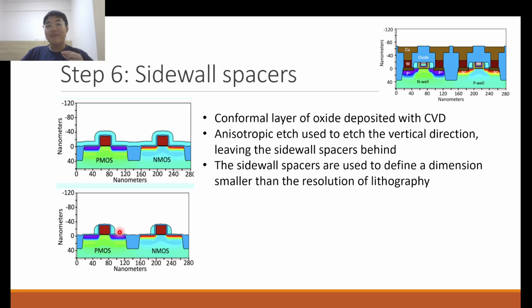So you can't define patterns clearly smaller than that dimension limit. However, using the sidewall spacer method, we can define features that are smaller in dimension than the resolution of your lithography systems. And so why are the sidewall spacers there? I didn't fully answer that question yet, right?